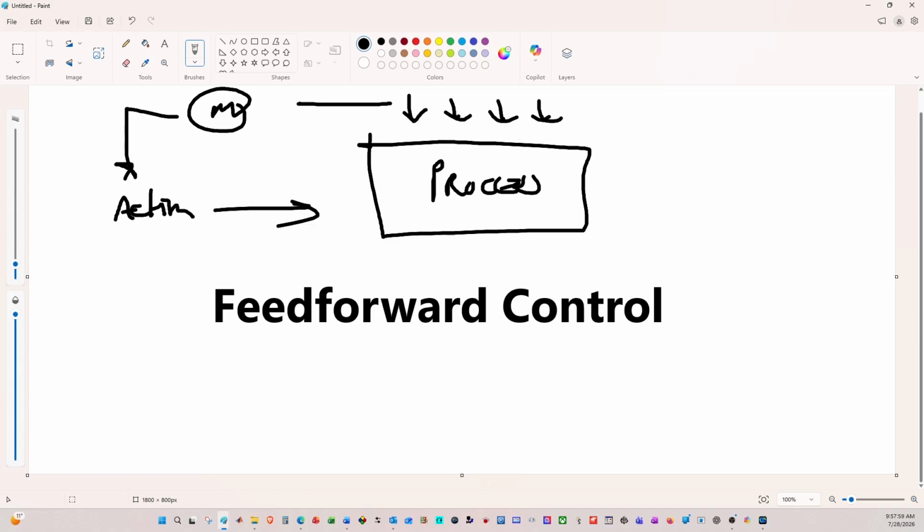By means of feed-forward control, the incoming flow is measured. The controller calculates how much extra steam or fuel is required. It then adjusts the valve immediately before the outlet temperature drifts. And please do go back to my video where I showed you combined feed-forward and feedback control.